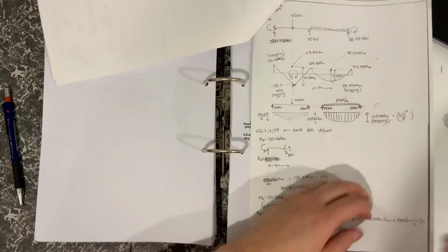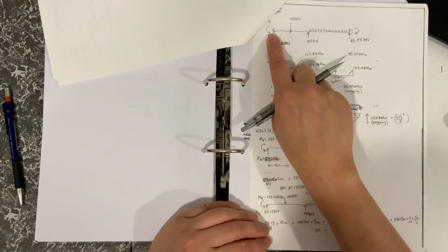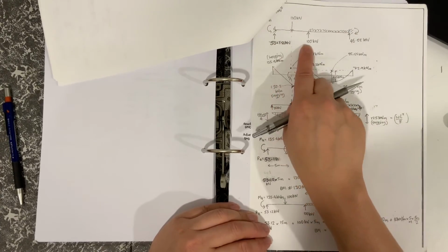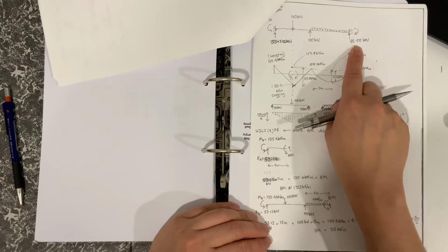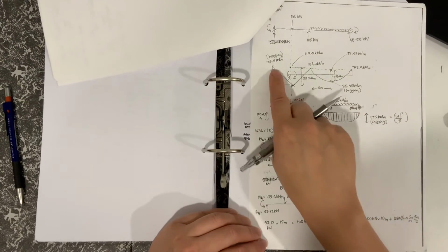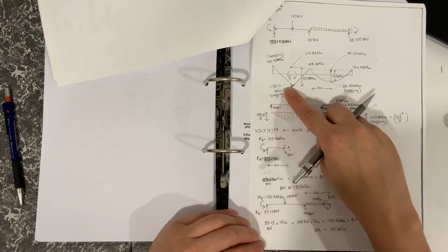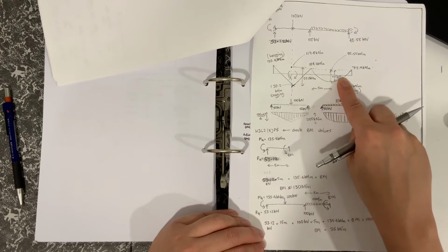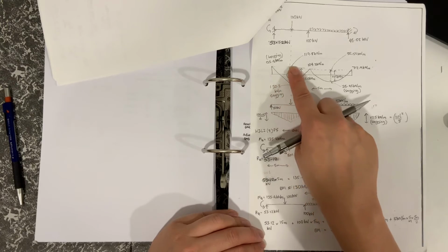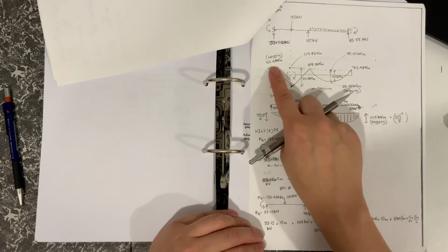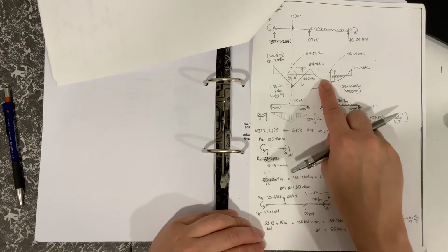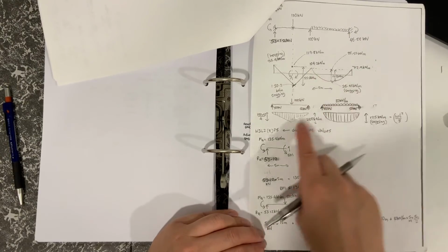Then here, which would be the final page, you've got the original problem with your reactions that have now been solved. You can see down here the bending moment diagram that's been drawn. You can see the reactant solution there, and then this is just added onto the active case to give the final bending moment diagram.